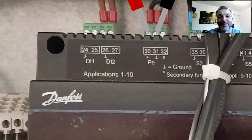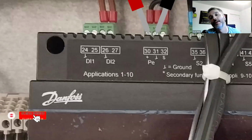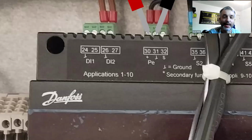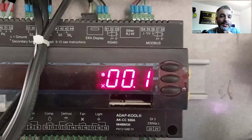But yeah, just bear in mind, DI1 and DI2 are volt free, and you can configure those inputs to do a whole range of things, from stuff that's quite minor to telling the case to run or not. So one of your key statuses is status 10. When you push that top button and it tells you the status code, it can say S10, and that is something's told me to stop.